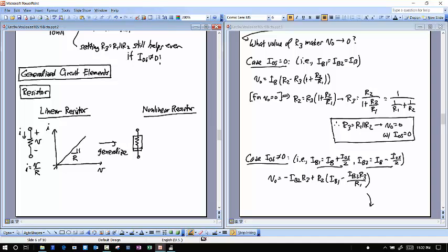So it's the same resistor symbol, except you put a heavy, solid bold-faced line where you have the negative terminal of this thing. Because now where the positive and negative terminal is matters for a nonlinear resistor. You'll still apply a voltage and you get a current, but now your current is a more general function of voltage. So for example, if I wanted to plot this, it may look something like this. This is current versus voltage. Then instead of a straight line, maybe I have some curve that looks like that, right? It's a very nonlinear curve.